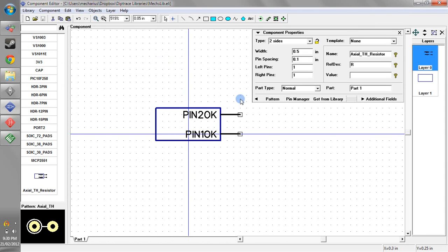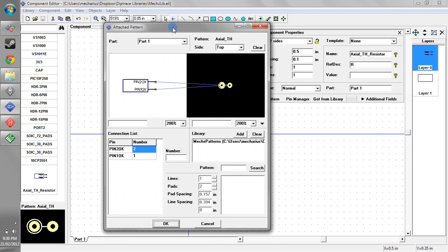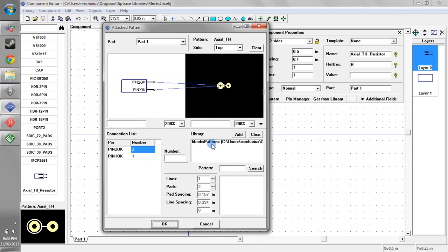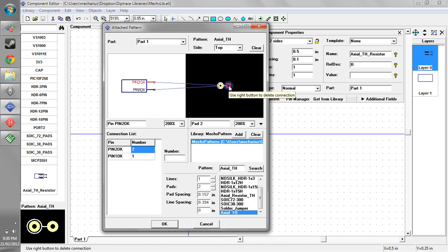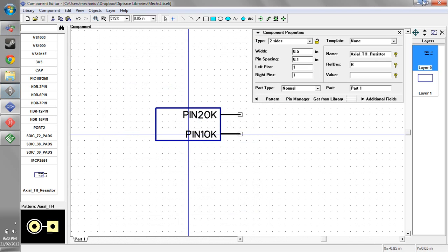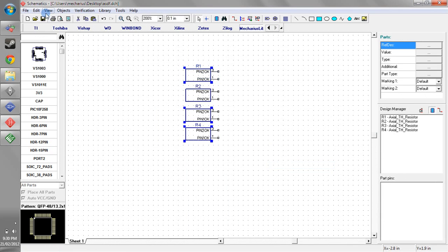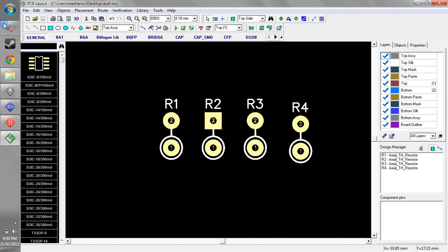And then we go back to the component editor. Okay, and we actually have to reassign the pattern. I found to, because you can see here it hasn't updated. So we go back to using this pattern button. Click again on our library to sort of refresh it. And you can see when I click that, this came back to the square or the rectangle. Click OK. Click save again. In our schematic, we have to update component type. Hit save, and then finally in our PCB we can renew design, and away we go. So there's a few more steps to that, but it's relatively painless.